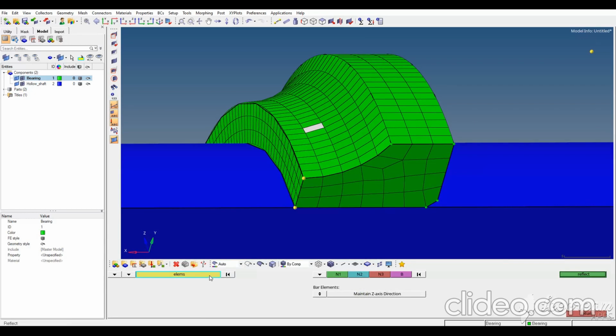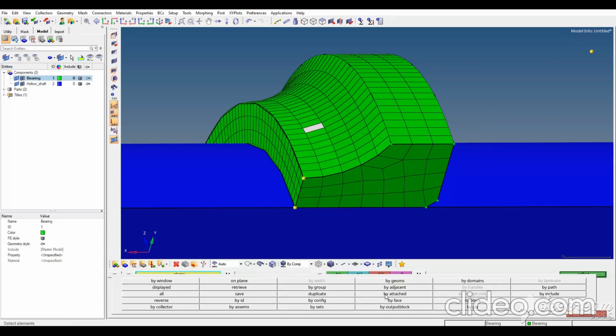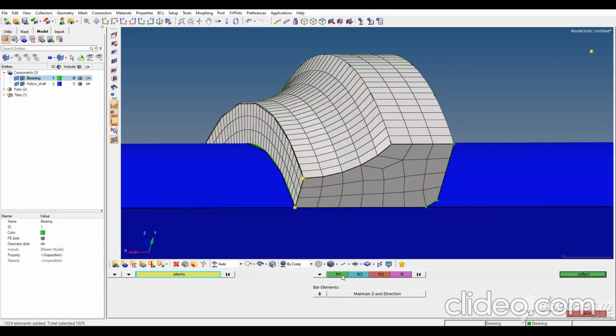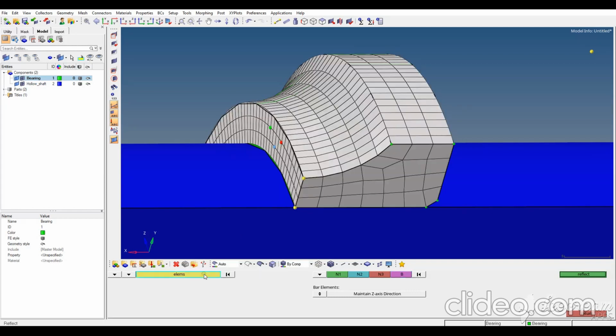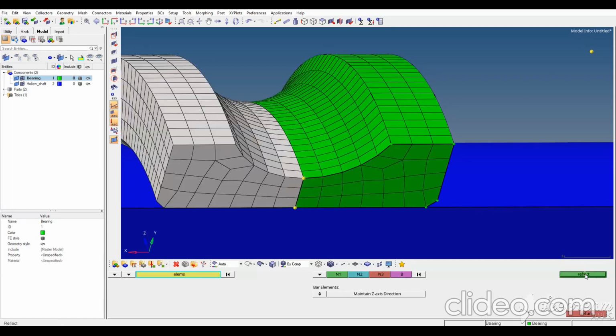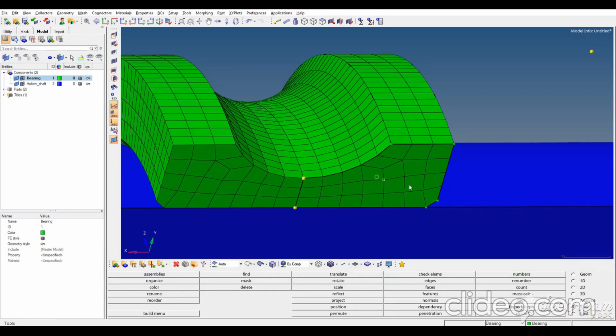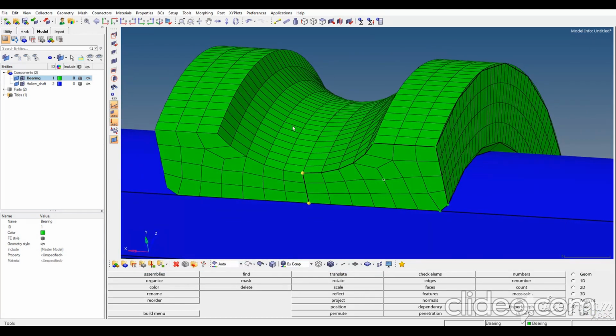and selecting the elements created by attached, and we are going to select 3 nodes of the plane. We are going to reflect these nodes and then duplicate the elements to the original component, reflect. Okay, although it looks fine to me, but